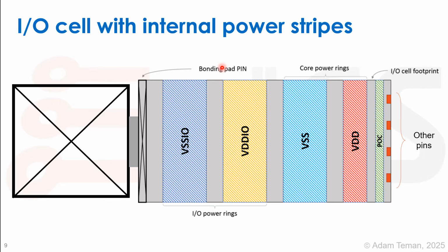So when we look at one of these IO cells, they actually have a specific structure, and this is going to be true for, I guess, all of the IO cells, not just the digital IOs. What we have here is the pad that connects to the outside world. This is going to be a different actual LEF or a different GDS. It's just basically a piece of wire that's rather big, and it has vias underneath it and more metal layers and so forth.